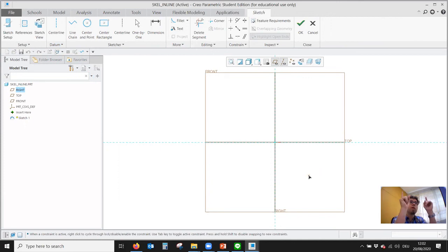Basically you have two different axes, two different points in your sketch menu. Maybe you have noticed that already. On the left side of the menu, you will have center line and point and coordinate system. And on the right, you will also have that center line and point and coordinate system. The ones on the right hand side you can use if you only need that inside the sketch. But I want to have a point outside of the sketch, so I have to use it on the left hand side. Problem is, in my menu, I'm not so sure. So anyway, I'll try it anyway.